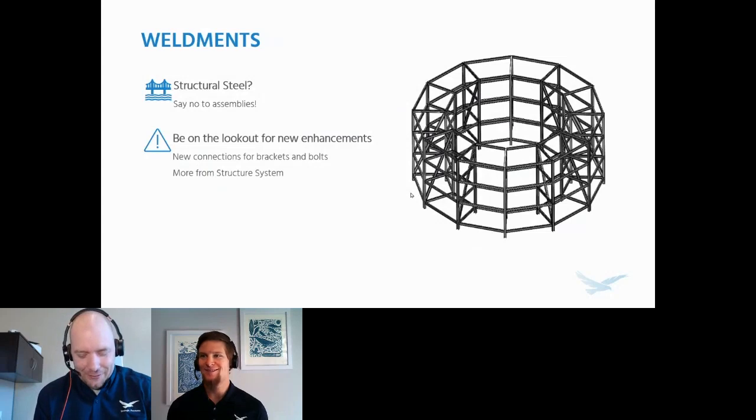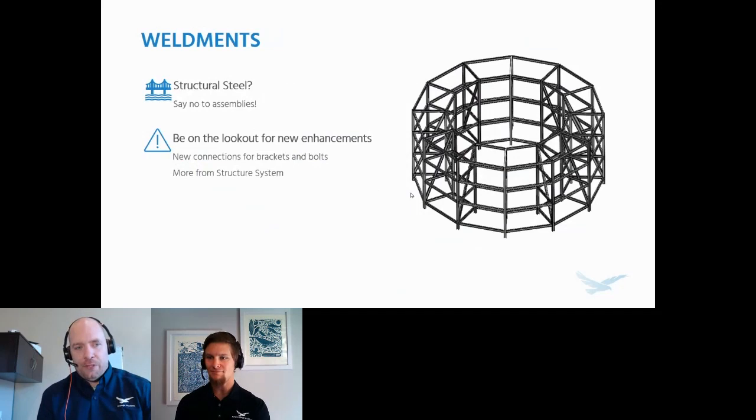All right. Weldments. Yeah, so this was, I think, probably one of the biggest things that was a huge game changer for me. I followed some pretty bad practices, not being taught really how to use SOLIDWORKS at all, being all kind of self-taught. One of the ones that I did was if I needed a piece of standard structural tubing or something like that, I would copy a part, right? I would have like my standard shapes and I would copy that.